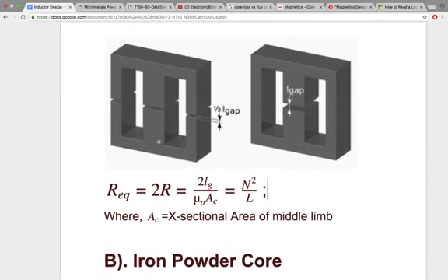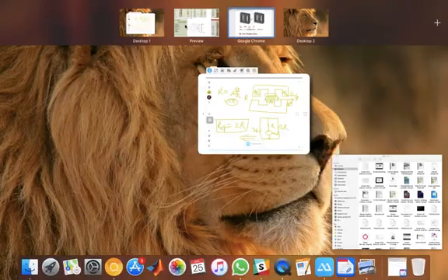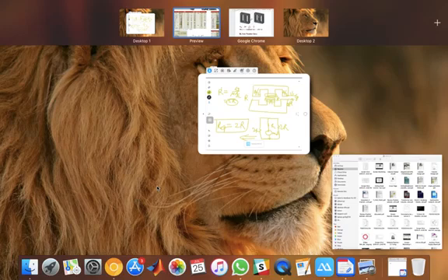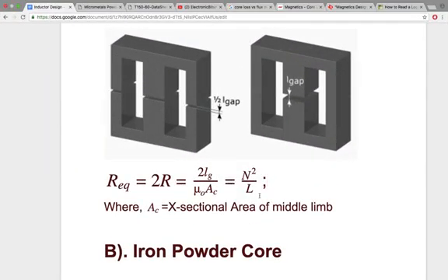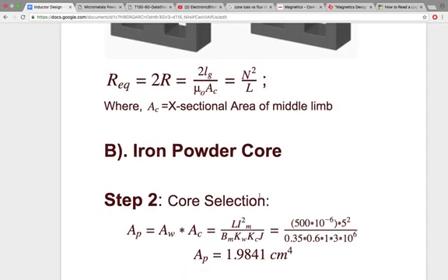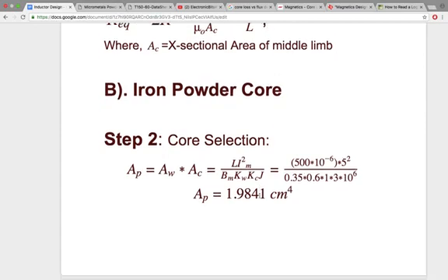Generally, for ferrite cores in high power applications, we don't use the toroidal core. If you have a distributed air gap, because of which we can have a higher reluctance, then we can definitely use the toroidal ferrite core. Why I'm saying that is because if you see the AL values, they are all pretty high. There is nowhere the AL value is low. Because the AL value is high, the reluctance of the cores is less, and because of that we need to have some air gap for increasing the reluctance.